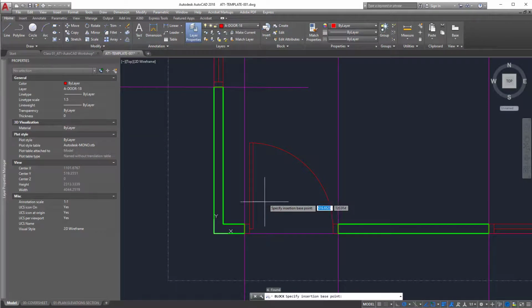Again, pick the point, and the point will be this corner. It generally is that corner that you pick. You generally choose what is known as the hinge side. The latch side is where your door latch or door handle is, and the hinge side is obviously where your hinges are. Most of the time you set your doors out from that side, usually because it's the side that's backed onto a partition wall or something like that.